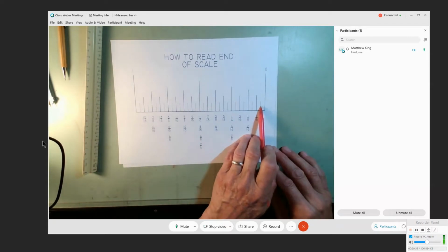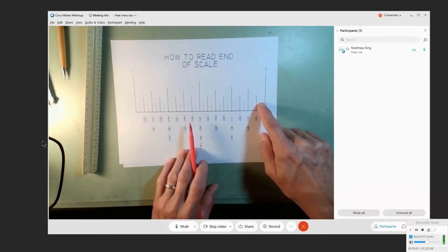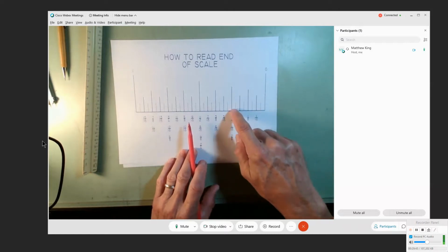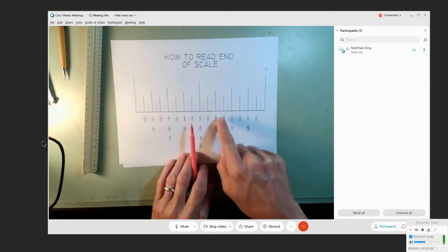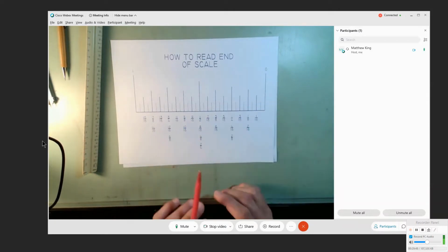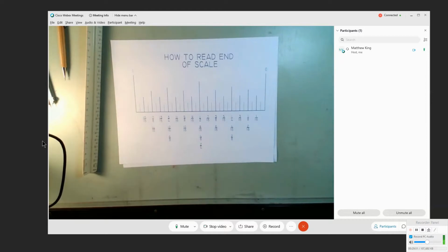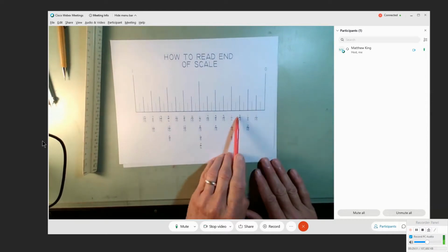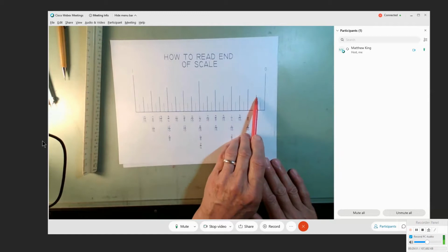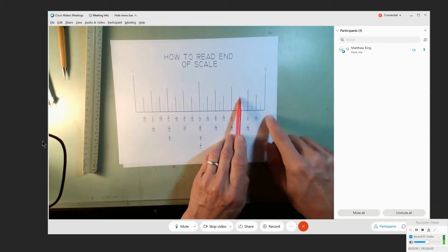These are 32nds. So you have to ignore the tiniest of these increments. They're not even labeled, right? So don't use them until we're ready for them. So if I were to say 3/16, that is labeled here. So it's 1, 2, 3, right? You skip the short one.